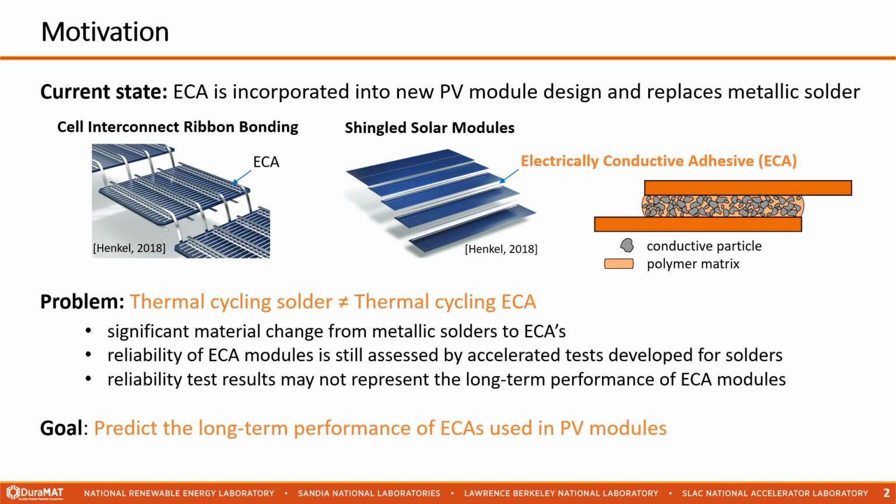In general, ECAs are composite materials consisting of conductive particles and a polymer matrix that holds the particles in place and establishes adhesion with the adjacent materials. The change from traditional metallic solders to ECAs represents a significant material change, but the reliability and durability of ECA modules is still assessed by accelerated tests developed for solders.